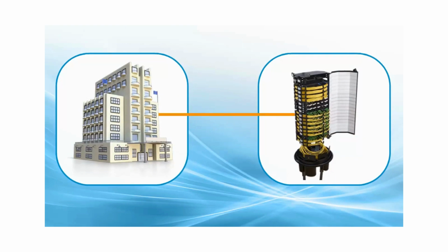In the centralized architecture using closures, the feeder cable from the central office is connected to a closure instead of an FDH at the fiber distribution point of the network. The closure performs as the splitter housing. However, while an FDH leverages connectorization as much as possible, the closure system is typically spliced together. Still, the closure remains accessible for adding splitters at a later time, so it's possible to deploy the network for an expected take rate and add splitters if the take rate increases.